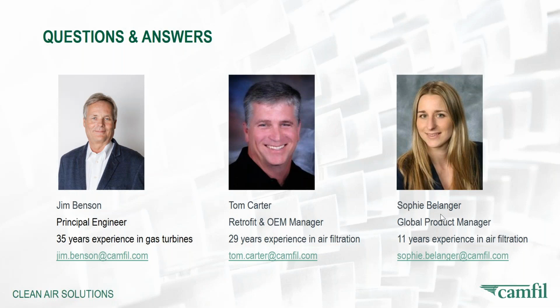Okay, fair enough. So depending on which treatment it is, let's take cooling first. You're cooling the air inlet to increase the performance of your machine because you're cooling the air, you're increasing the mass flow into the turbine. Higher mass flow means more energy, higher output from the machine. The only impact on that is there's a slight increase in the airflow per filter.